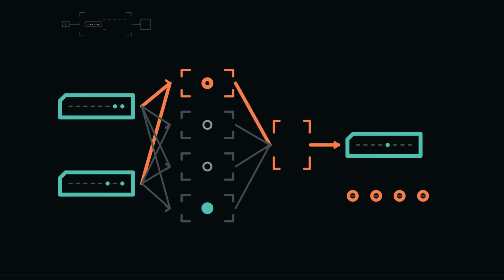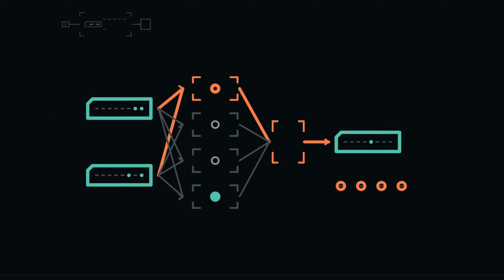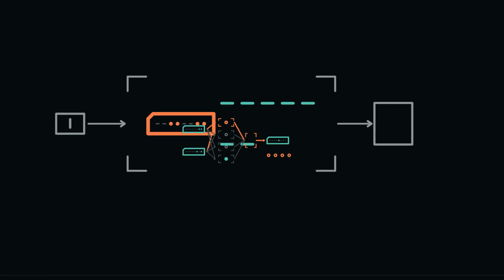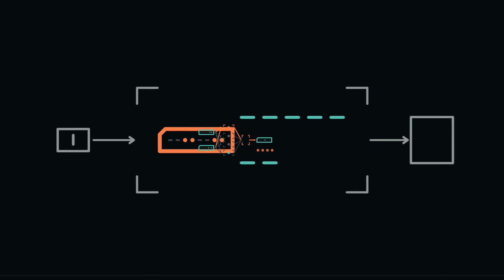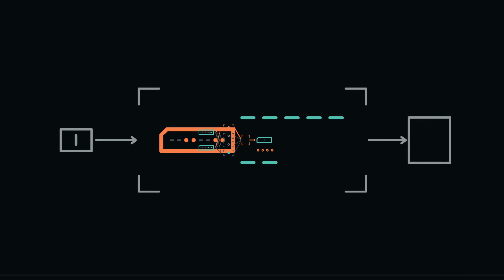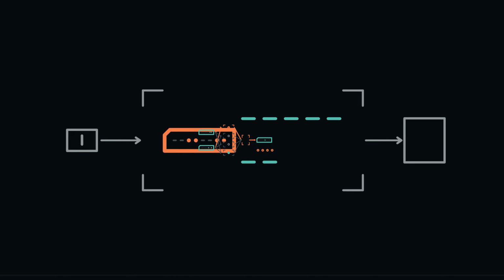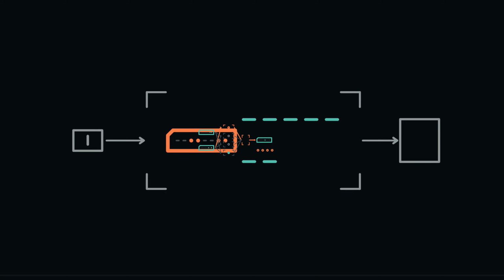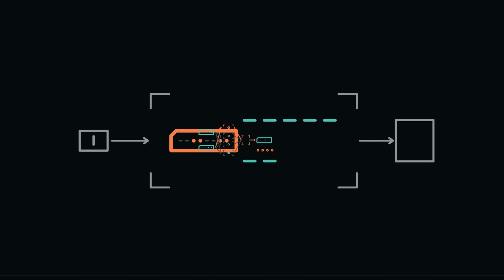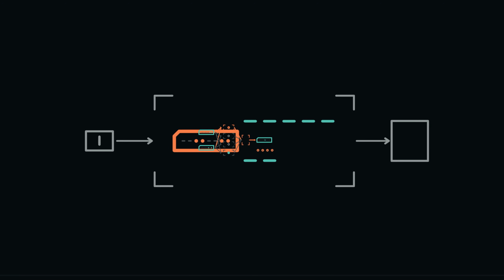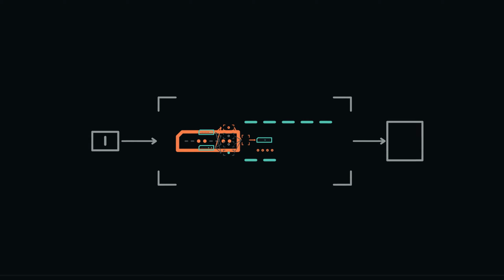The machine can now preserve bytes, select them, transport them, and transform them, but someone still appears to be choosing every control line by hand, which register drives, which operation runs, and which destination captures. To remove that hidden operator, the choices themselves must be represented as stored patterns. A program will place instruction patterns in memory, a program counter will select them in order. The controller will turn their fields into the exact permissions we have used. Control is about to become encoded state rather than an unseen hand outside the frame.